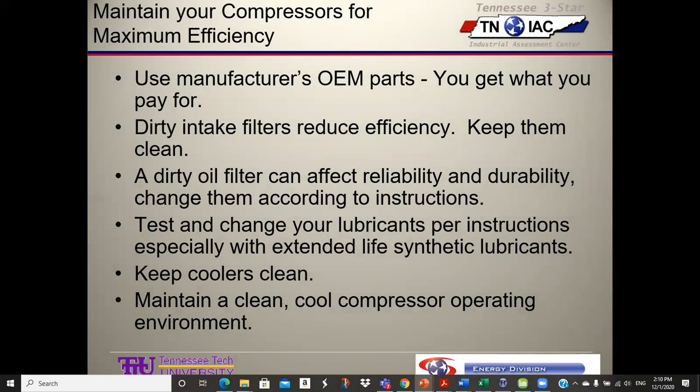Some other recommendations. Sometimes non-OEM parts don't work as well, hurt your efficiency. Dirty intake filters reduce efficiency, keep them clean. Dirty oil filters, you need to change oil and replace it as recommended. Test and change your lubricants per instructions, especially with extended life synthetics. Keep coolers clean. Maintain a clean, cool compressor operating environment.